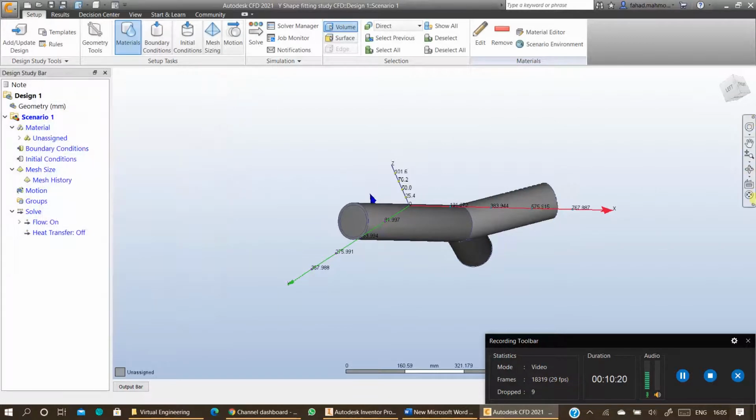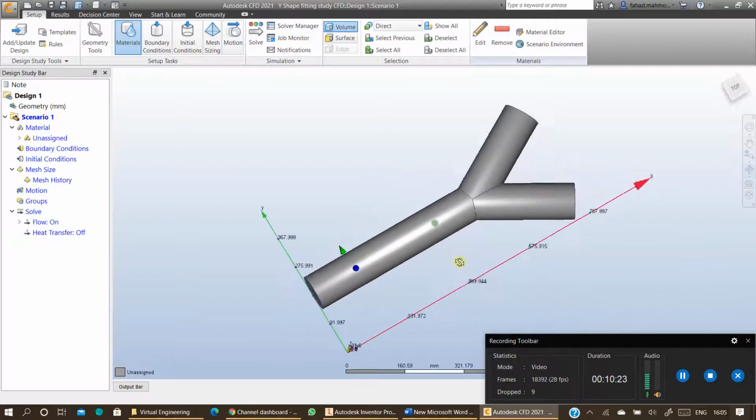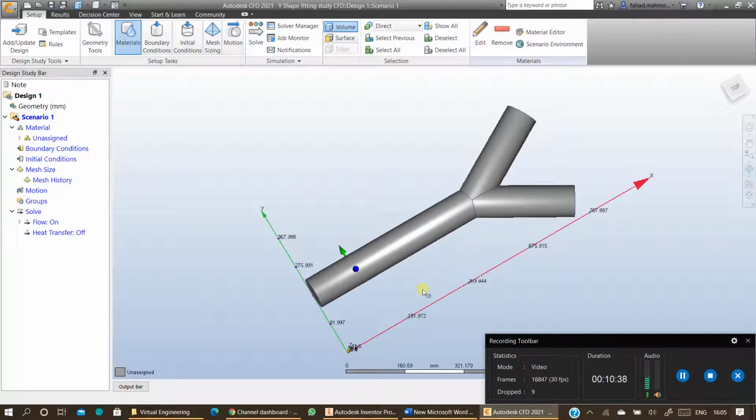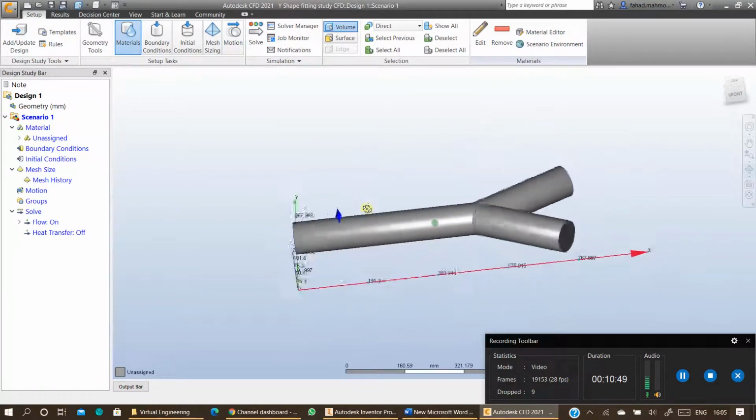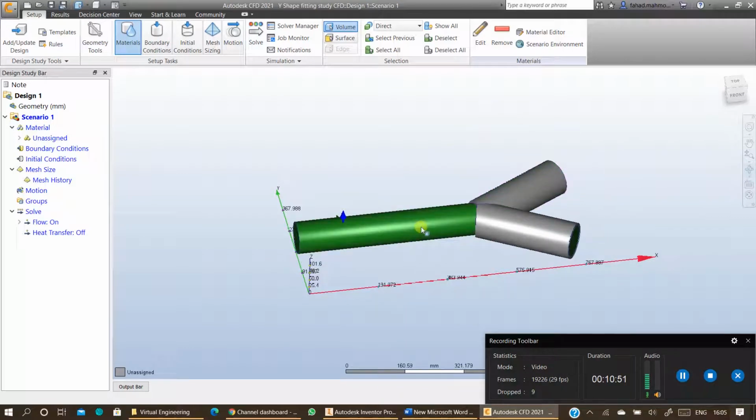At this point, you can double check your model for any existing errors. You can check whether the void is according to your requirements. So press escape, press Ctrl on your keyboard, and you can minimize all the shapes like that. So this is the void which has been created by CFD analysis tool. To bring your model back, you can scroll up to bring your model back, or just click the middle mouse button by pressing Ctrl.